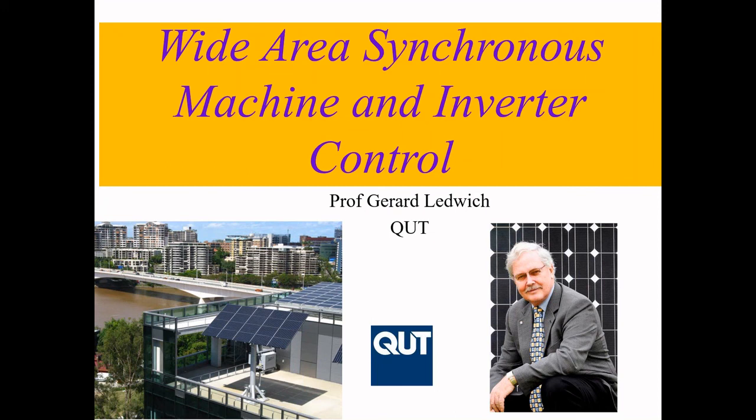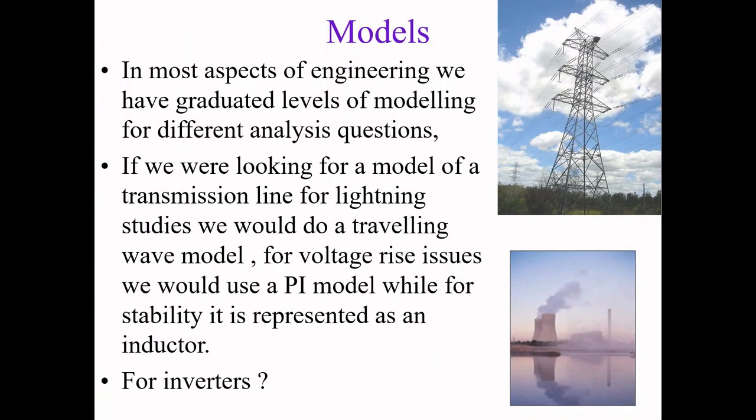Then along the way, I was hearing about bunches of inverters in northwest Victoria that had to be scaled back in their power output because of oscillations. So that's part of the motivation for the development. The other thing that was learned along the way was modeling. For inverters, we haven't traditionally had a big range of models available, and so if you wanted to validate a particular company's design, you really should just do a complete full state model of the system.